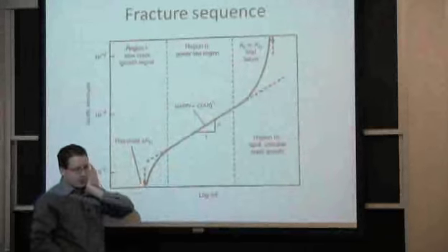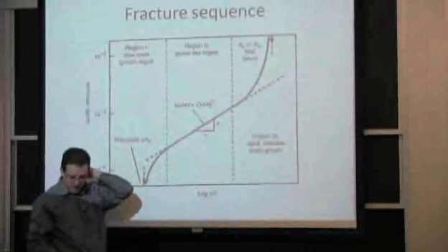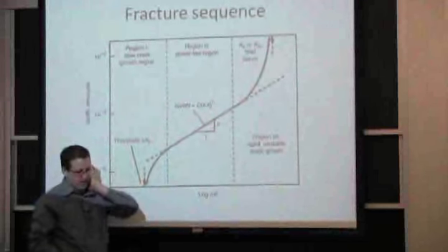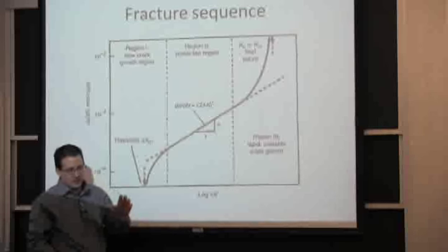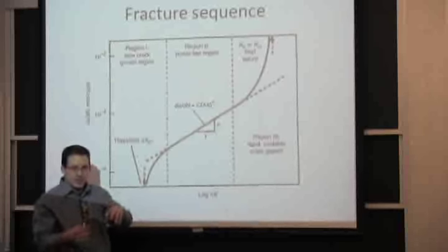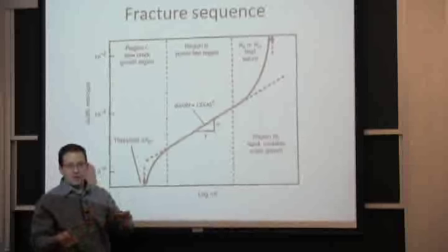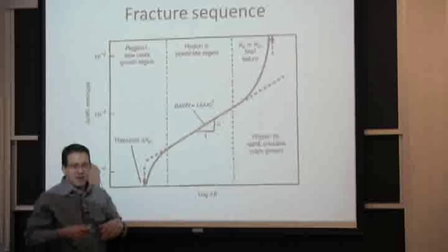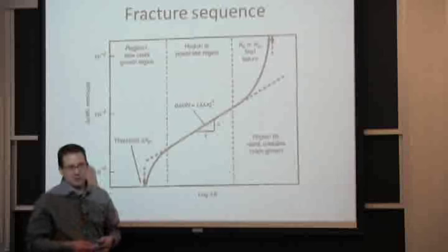And when they put in stabilizers, sometimes it's to help prevent these cracks that are forming at the tip, where you have some plasticity, from growing too fast. The idea is to add crack arresters, so you can have more plasticity and absorb more energy.